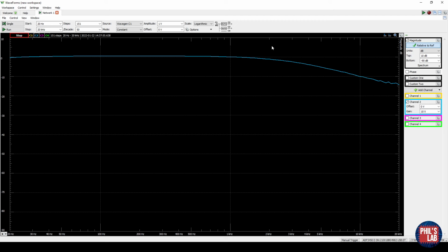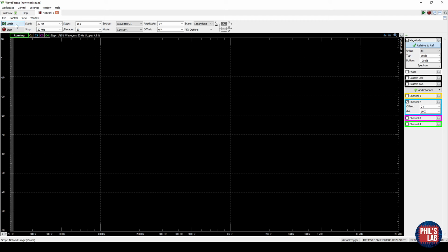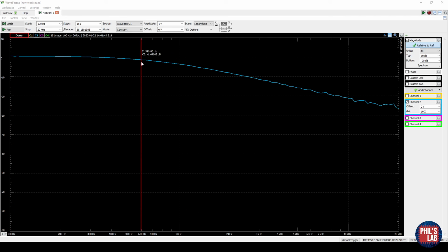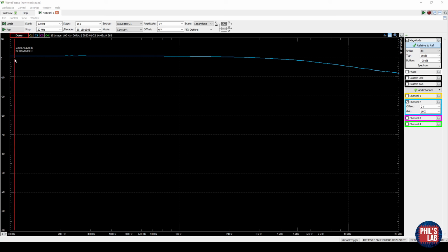So if I change the cutoff frequency now, just using the potentiometer, and then re-click to do a single measurement. So I've moved my cutoff frequency quite a bit lower now. I can use this measurement tool to find the -3 dB point. Now keep in mind, up here I'm at about 0.4 dB, so it's -3 dB down from that. It's about -2.6 dB, and that's at about 1.1 kilohertz. Now let me just readjust my potentiometer and do another measurement. And now I've adjusted my potentiometer, done another reading, and again I can find my -3 dB point, so it's about 800 Hertz, and of course I can turn that the other way as well. And here you can see the cutoff frequency has moved. So again, -3 dB from here, so -2.6, somewhere over here, and it's moved to 6.3 kilohertz.